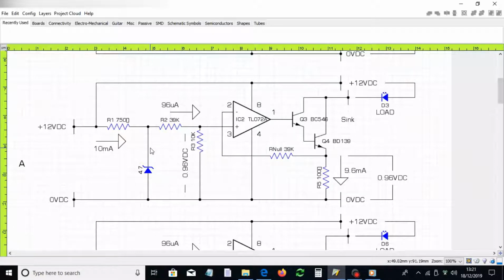But all in all, Zener diodes have been superseded by integrated circuit reference chips, some of which can get very expensive. In days of old, when nights were bold, this type of instrument would use something called a Weston cell. I've worked with Weston cell devices before. They are a chemical product, and this is of course where standard references started from.